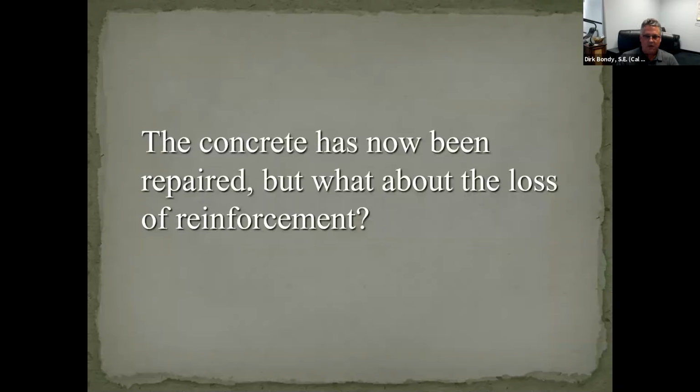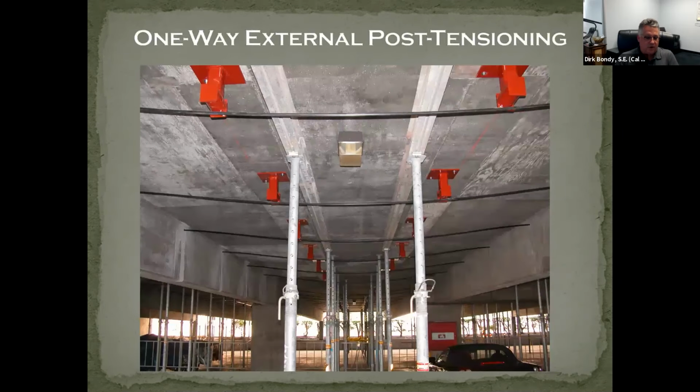So now you've repaired the concrete, but what about the lost reinforcement? And that's the big question. You have to determine, have you lost enough reinforcement that you need to apply more reinforcement? And that's where the external post-tensioning comes in. Concrete's now been repaired, so you feel good about it. Hopefully you've sealed the top of the deck, so corrosion has been arrested, but you have to decide, do you have enough strength?